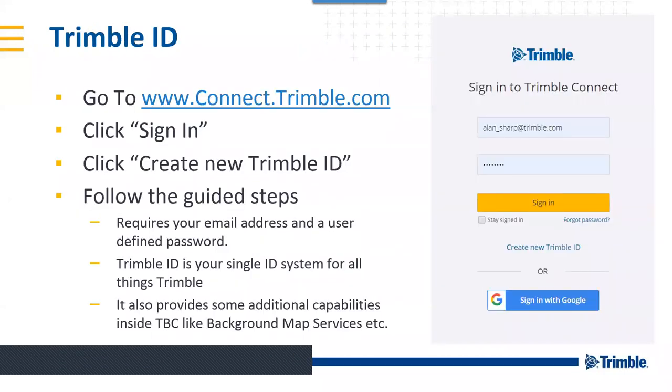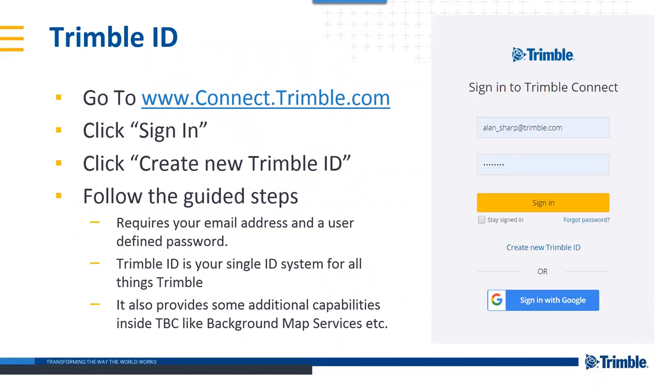For Trimble ID, if you don't have one, then go to www.connect.trimble.com, click the sign in button, and once you've done that, at this dialog that's shown on the right here, you hit the create new Trimble ID button, and that will then take you through the steps to create an ID, and that basically requires you to input your email address and define your password that you want to use, and that will then become your unique ID for all things Trimble, including running some additional functionality in Business Center like the background map service, but also will allow you to use the TML status and to start accessing all of the TMLs through the Rockpile TML management service.